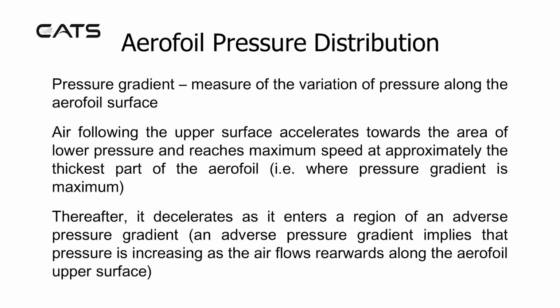Aerofoil pressure distribution. Pressure gradient. This is a measure of the variation of pressure along the aerofoil surface. Air following the upper surface accelerates towards the area of lower pressure and reaches maximum speed at approximately the thickest part of the aerofoil, where the pressure gradient is maximum.